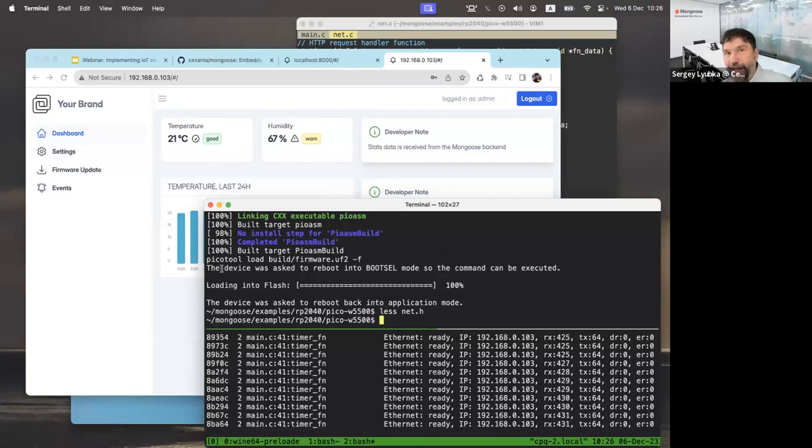Other clients can say, I subscribe to this topic, and any data published on that topic will be relayed by the MQTT server to that device. This is a very simple mechanism, but it allows embedded devices to be remotely visible without any non-standard tricks like port forwarding. It's a standard protocol.